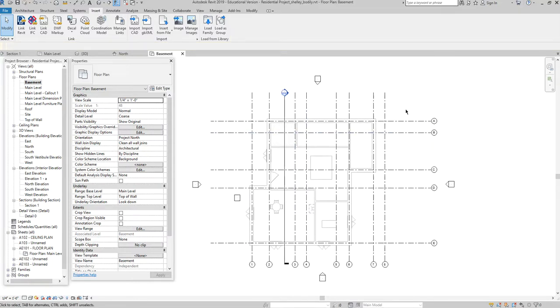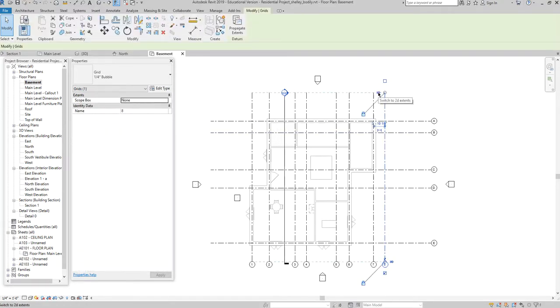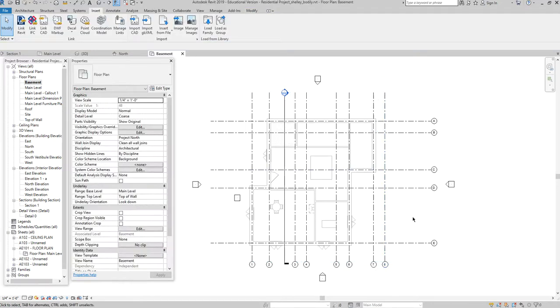It's either something visual is just turned off, because they're obviously there and defined, or the other thing I suspect is that the grids are only existing in a 2D environment instead of a 3D. But I'll come look if you can't get it worked out. The other thing you could try doing is deleting your basement level and regenerating it, recreating it. Something could have been thrown off when you did that.